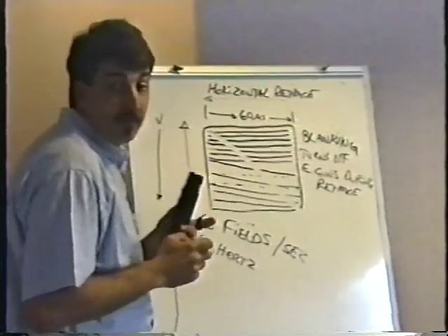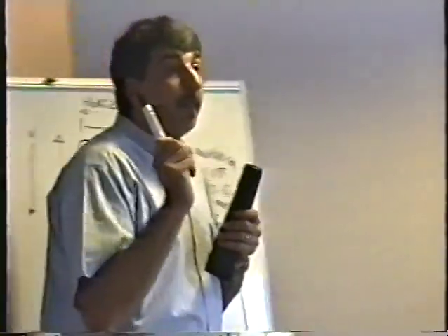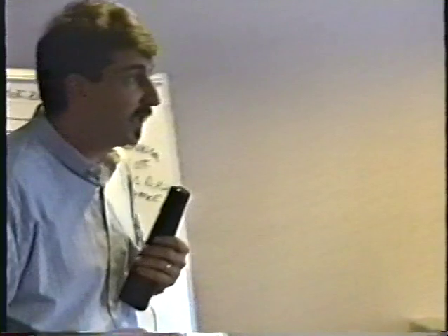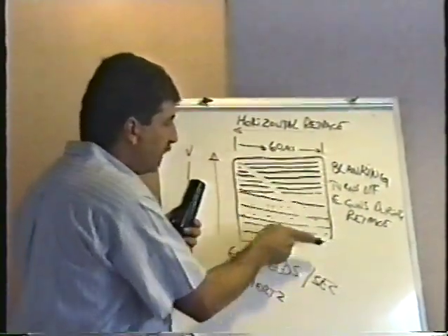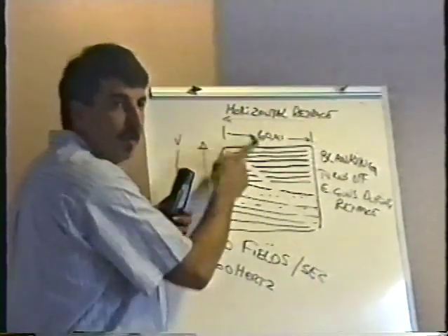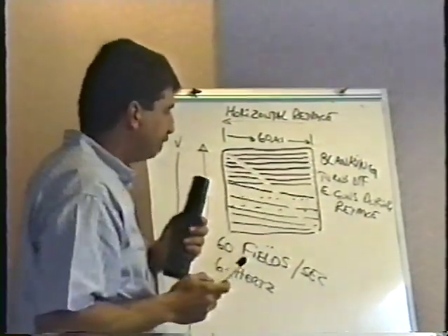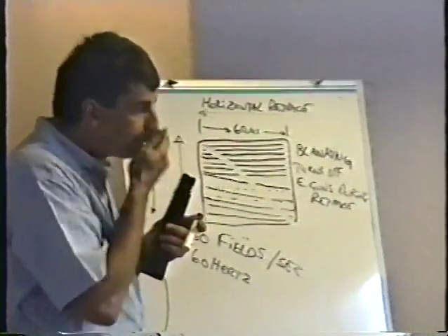It's the same frequency, but the monitor does not depend on our AC power to get that 60 cycles per second. If that was true, you couldn't have battery-operated TVs, could you? There is a circuit inside the monitor that generates that 60 cycles per second, and we'll look at it later on in this lesson. But 60 times a second, the beam moves from the top to the bottom and then back up again, over and over, filling the whole screen full of these lines.